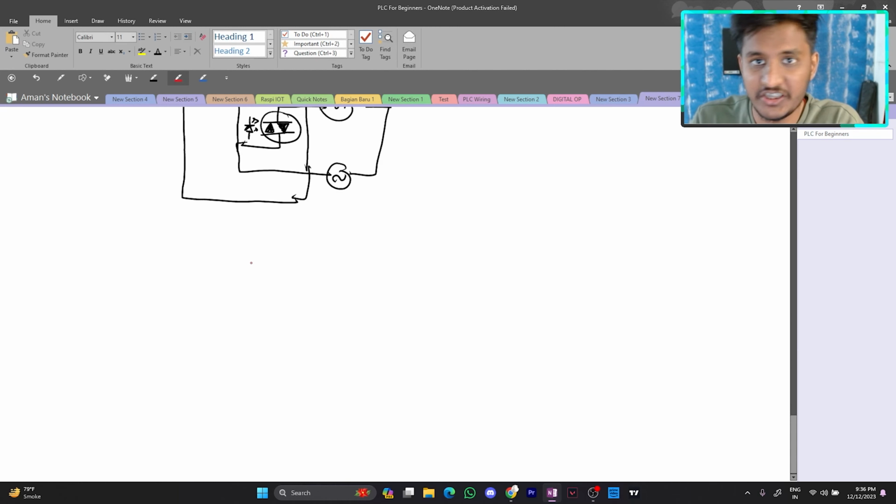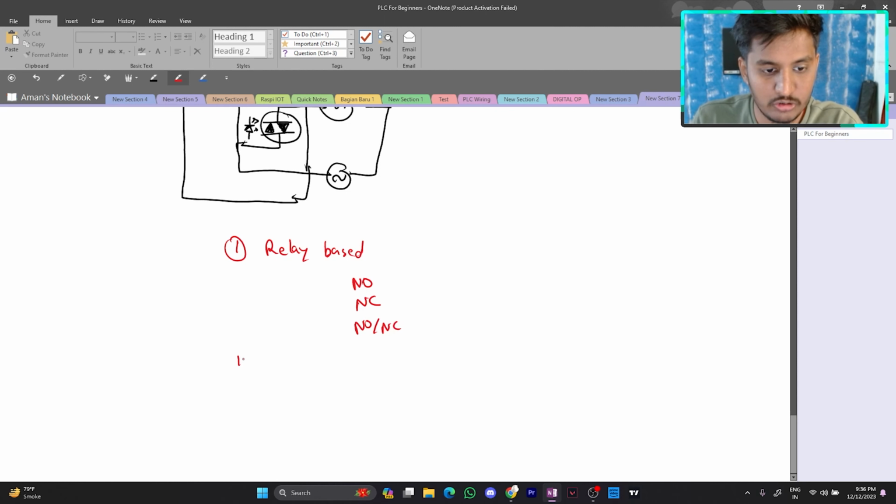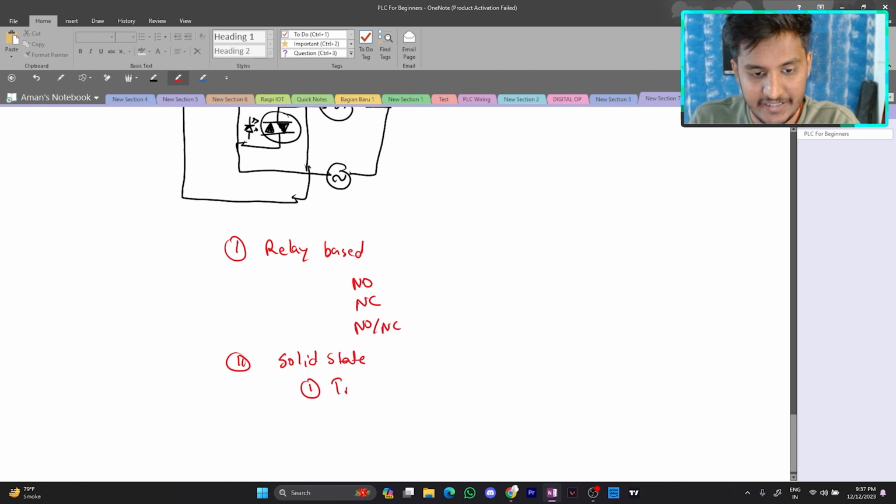So in this lecture of digital output, we have covered both the digital outputs. First was relay based, in which we saw all three different types of relay: NO, NC and NO/NC type. And also we covered the solid state digital output, in which we covered TRIAC and also transistors.